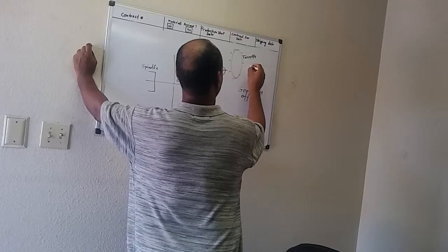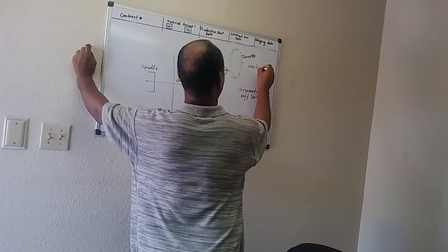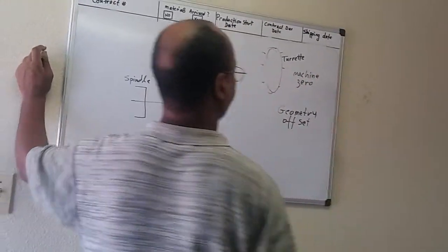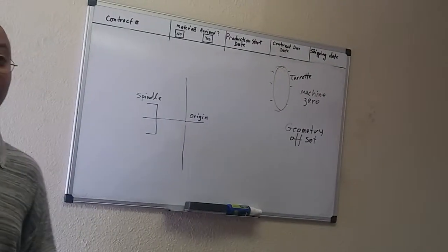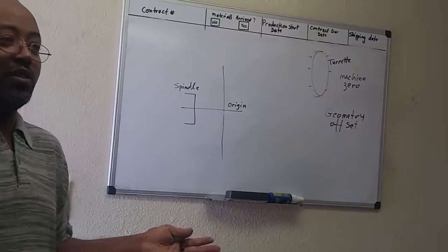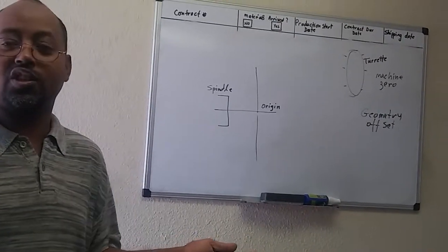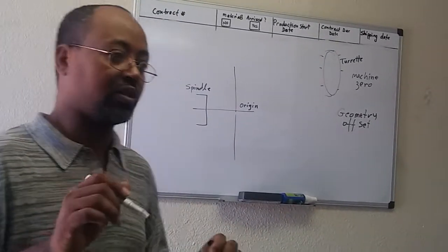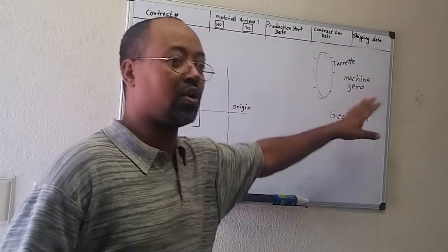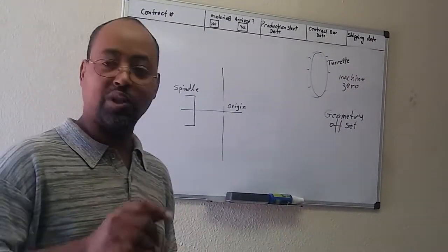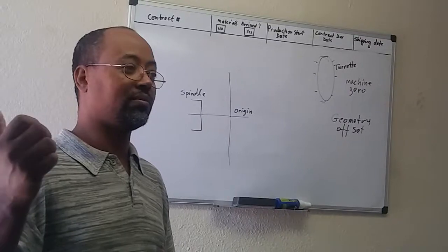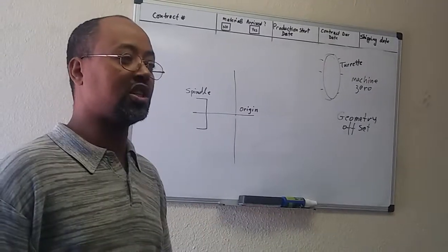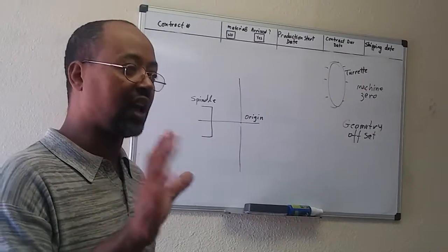So if my machine zero, when people design the machine, they can only tell the machine go home, and that home is considered zero. Those parameters, those values for the machine zero are held. When my machine is not running, I turn it off and I go home. Those parameters are held by batteries. There are batteries in the back of the machine that basically keep those values.